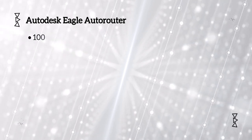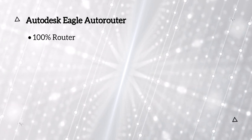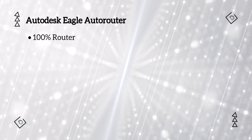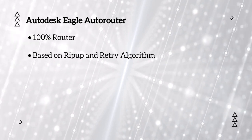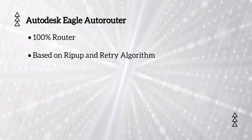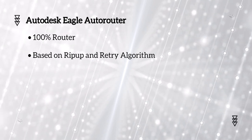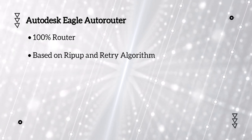The Eagle Autoroute is a 100% router. This means that boards which, in theory, can be completely routed will indeed be 100% routed by the Autoroute. The Eagle Autoroute is based on the rip-up or retry algorithm. As soon as it cannot route a track, it removes pre-routed tracks or rip-up and tries it again or retry.